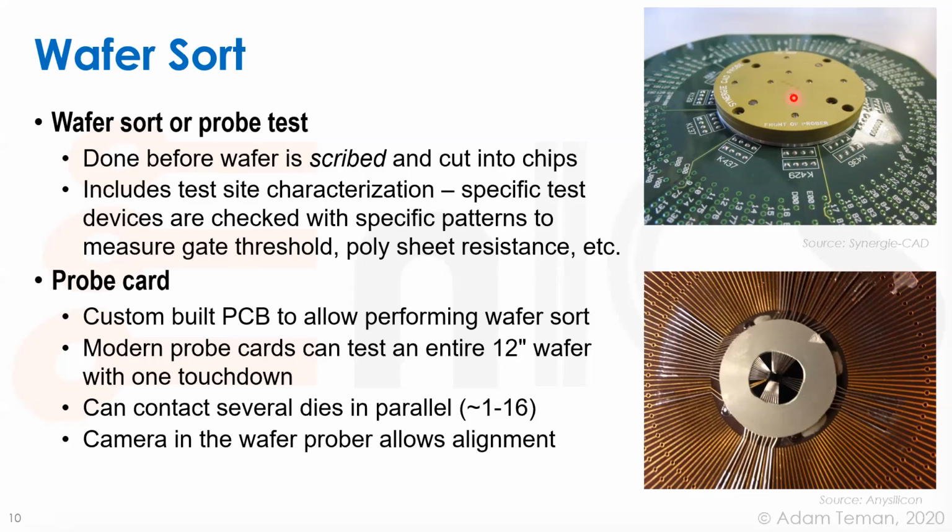Actually, today you do not always do it. It's economical; it depends what the cost of the package is. If the package is very expensive, then you really want to save the package. Sometimes when the yield is extremely high and the package is not that expensive, you skip wafer sort. Okay. But it's an economic decision.